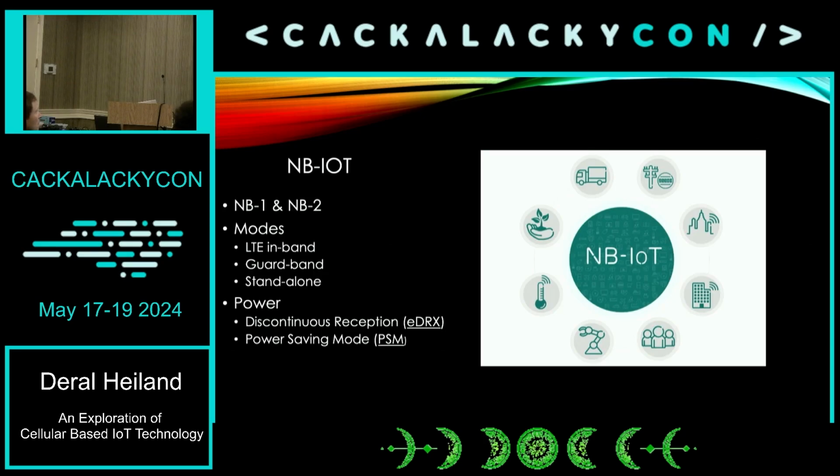They often have two types of power controls in them. One is discontinuous reception. Obviously, you don't want to consume power, so if you're not transmitting anything, you don't keep signaling, which reduces power consumption. The other is power saving mode, and you'll actually see it happen on this device. It will come up running, do a bunch of transmissions, then power the module down. That's done to improve power consumption on these devices.